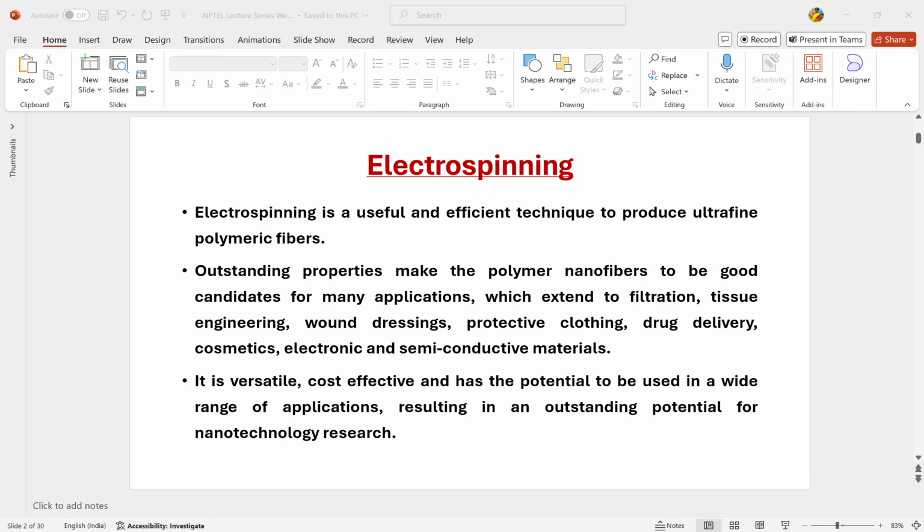There is some kind of a specific fluid which you provide inside, and which is thrown towards the opposite side, the plate. The fluid will be polymer. Based on the type of work you're doing, based on your application, you are going to choose a polymer. That polymer will be pulled into strings, which will form your nanofibers, at very high voltage. Yeah, 50,000 volts it was stated, I guess. So very high voltage.